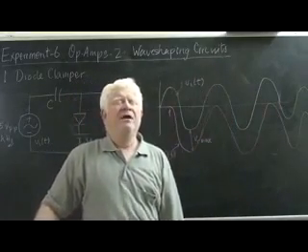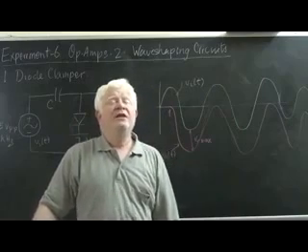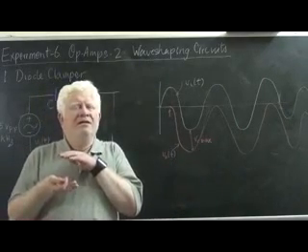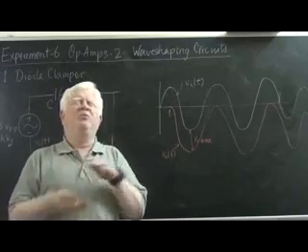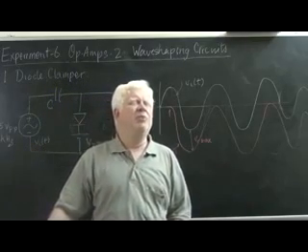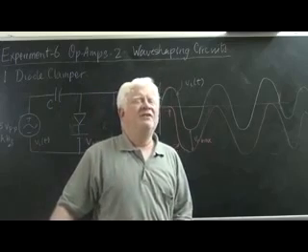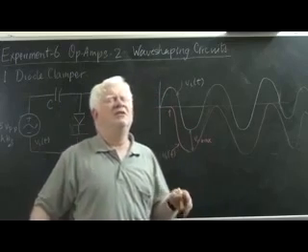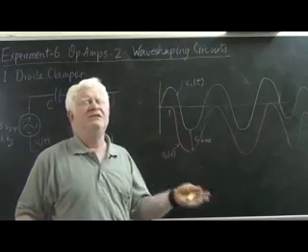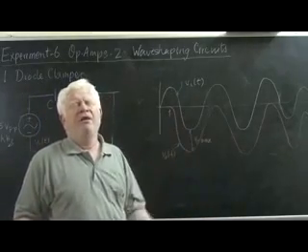The purpose of clamping is to force the output voltage to assume a certain DC level with respect to the input. But in this case, the DC level of the output is not adjusting itself with respect to changes of the input.